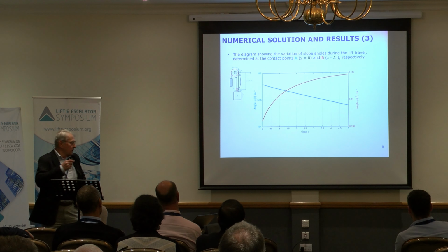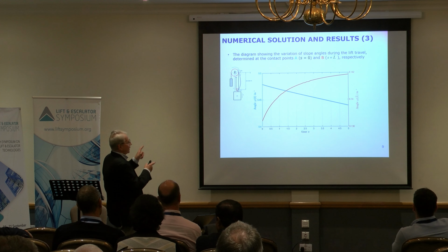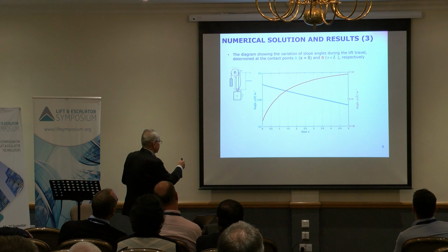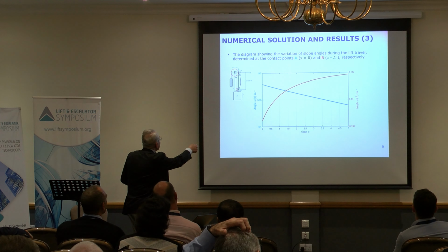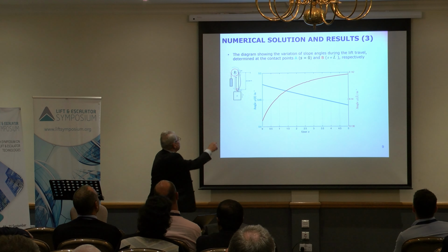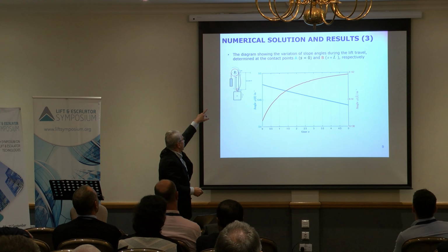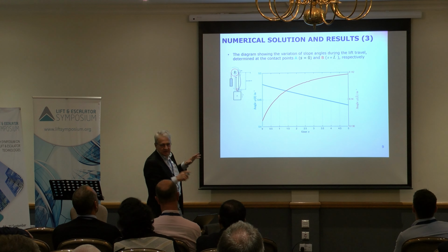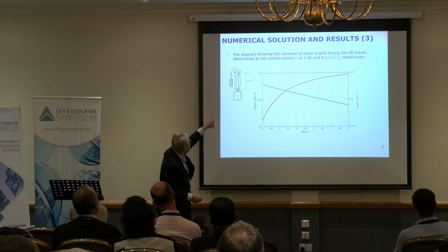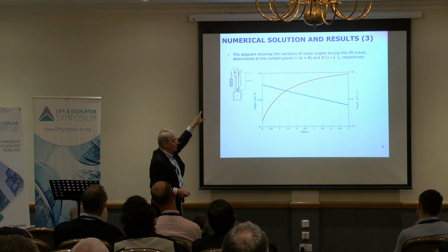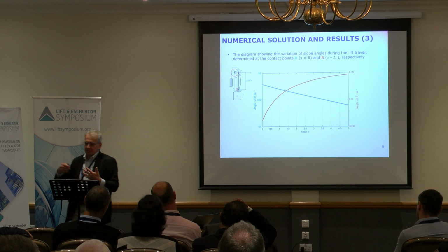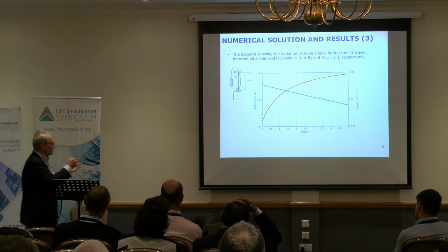First of all, we calculate for the given set of data there the angle here. So that's the angle which we didn't know. This angle changes slightly at the top, at the bottom. At the top is decreasing slightly. At the bottom is increasing slightly. It's about 5 degrees at the top, at the sheave, and the bottom about 6 degrees. Small, but meaningful.